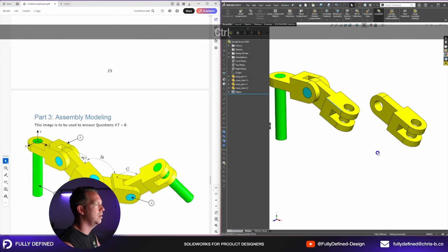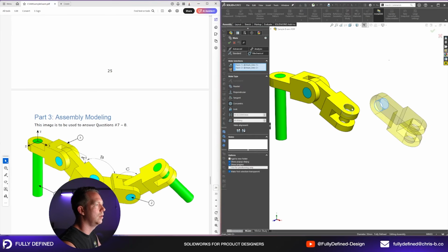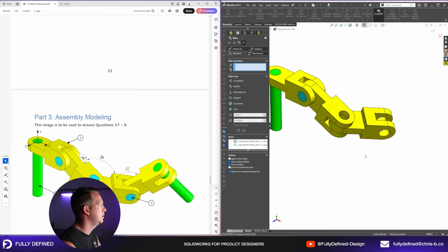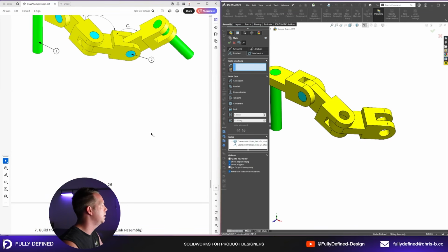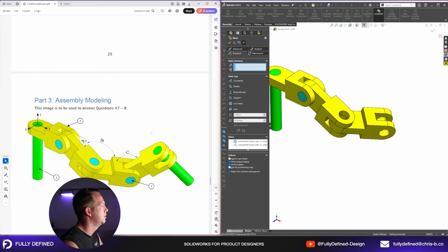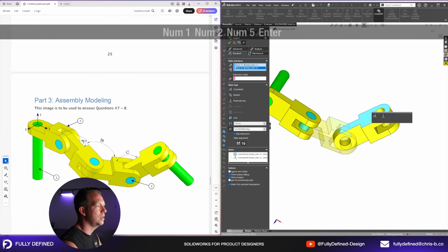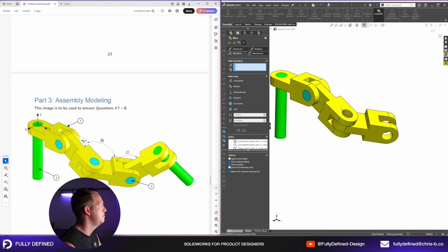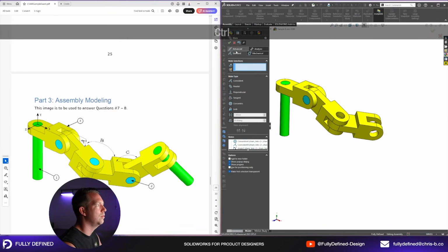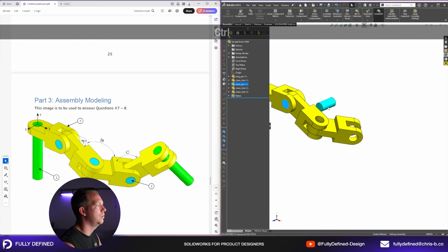Let's just get the other yellow parts in. So I'm going to get one of these here. And this is going to have an angle B of 125. So that's from this face to this face. Now this one does work, so I can put the exact number in. And then I want to get another one of these. So I'll put one of those in.